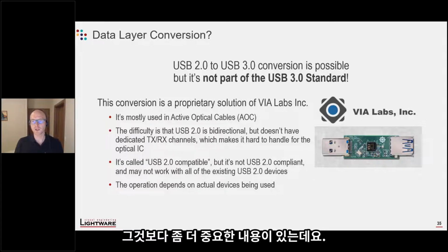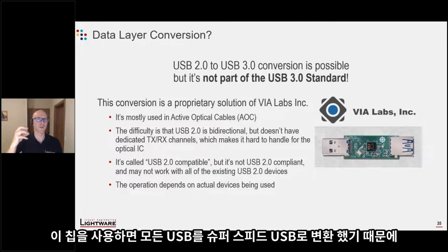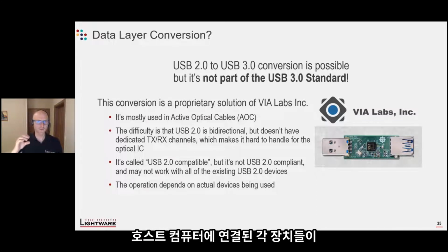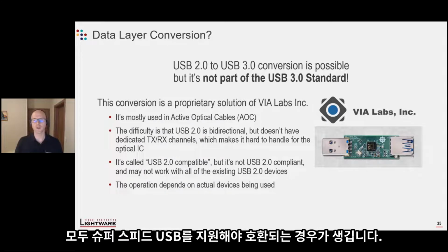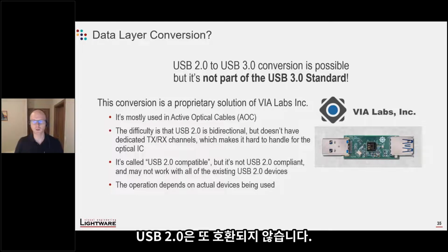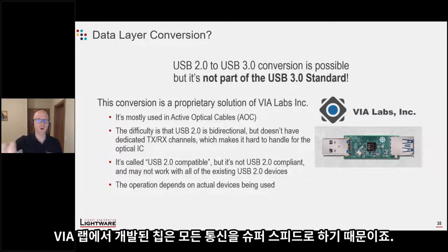And one important message here is that since it converts everything up to super speed USB, the host computer to which you connect this device, or the port where you connect it, needs to be super speed USB. You cannot connect it to USB 2.0 ports because the output of this VIA Labs chip only communicates through super speed USB.